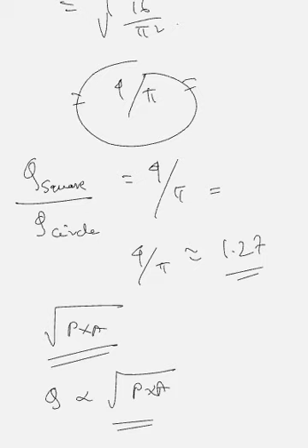And also remember, for an infinite fin the tip temperature is assumed equal to ambient, and that simplifies the solution, and this is why the formula becomes neat. So whenever you see an infinitely long fin, all properties constant, compare heat transfer, immediately apply this method. So the heat transfer ratio of square to circular is 4 by pi, so the correct answer will be option A. This is a beautiful example of how geometry influences heat transfer performance.